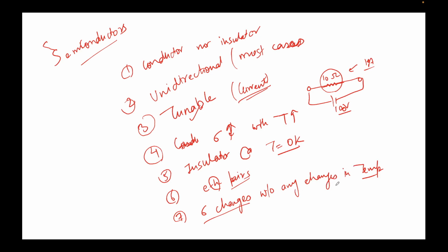Just adding more doping. Very good. So doping is the cause, correct? Yes. You change the doping, this is the cause, and the effect is that conductivity changes. We'll see how it does. And the band gap varies? Band gap varies only in case of high doping. For typical dopings, band gap does not change. That's at constant temperature again.